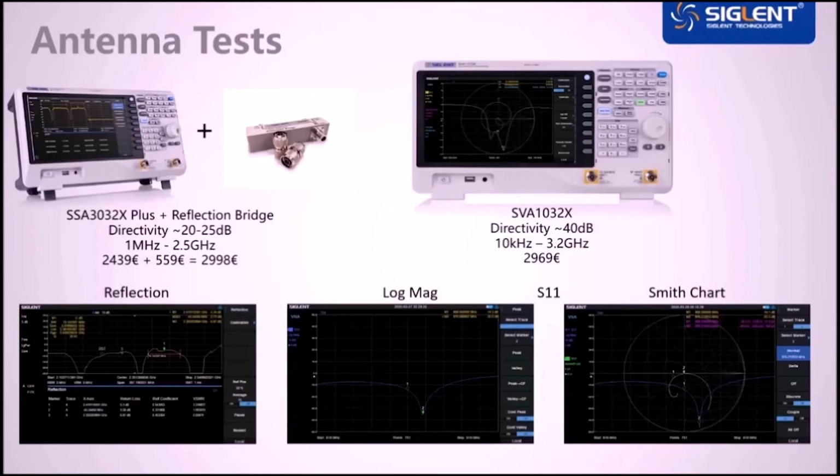One more thing. If you buy antennas or your own design is produced by some kind of PCB manufacturer, you should always have regular incoming inspections for your antennas. I had many customers who had very bad surprises with the deviation of the individual batches and had some product recalls. Therefore, try to keep in mind that antennas should be tested frequently.